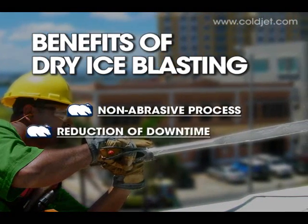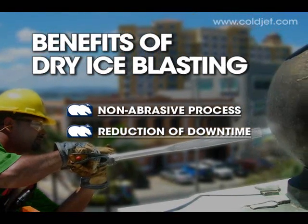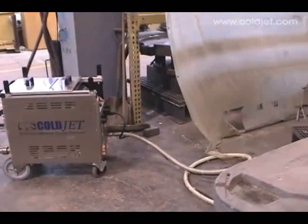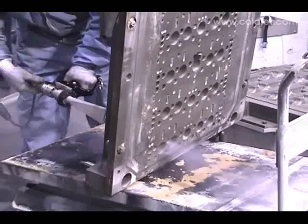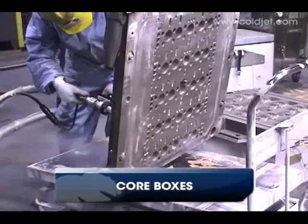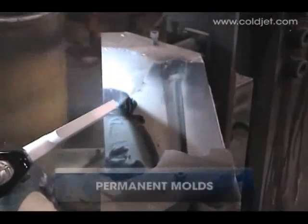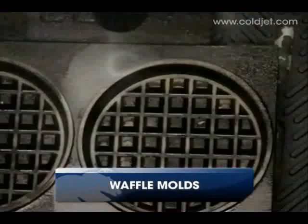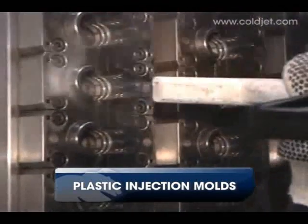The most significant benefit for many users is a substantial reduction in downtime. Dry ice blasting is most often used right out on the shop floor. Cool down, masking, and disassembly are not required. As an example, in the foundry industry, dry ice blasting is ideally suited to clean hot core boxes and permanent molds in place. Mold cleaning is a common dry ice blasting application, not only in foundries, but also in food manufacturing and in rubber and plastics molding.